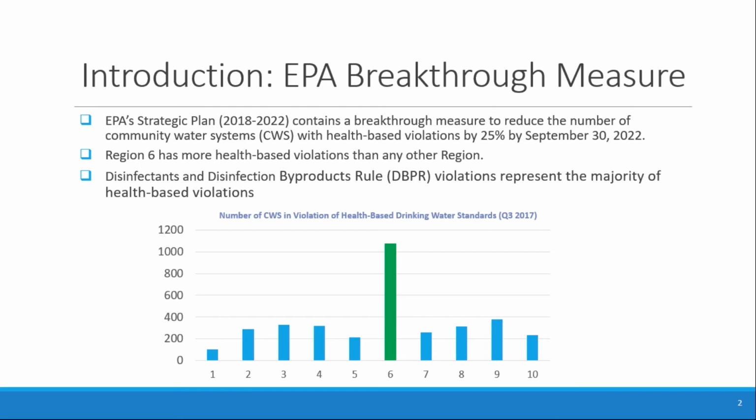Now, what's noteworthy about this measure is the focus on community water systems. In the past, our focus was on percentage of population served that met health-based standards. And what that did was it basically masked the small systems. And since this is more of a small systems webinar, you can see the dramatic impact. In EPA Region 6, we had about a 94% population that received safe drinking water that met all of our health-based standards, working under that metric. When we shift from a population-based to a community water system-based, you can see that Region 6 doesn't look so good all of a sudden.